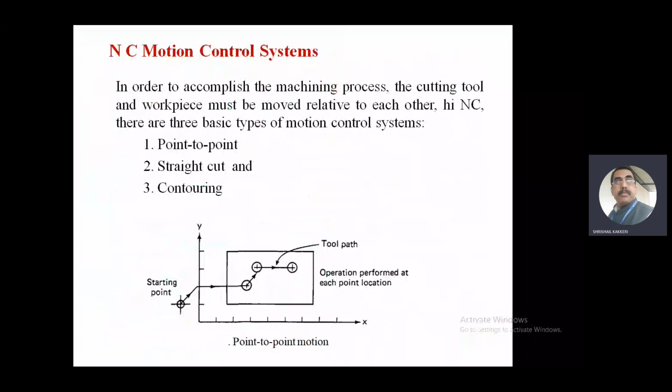Slowly it will be going. So what happens if you have contoured motion? It doesn't have any application, correct? Unnecessarily it will be wasting time. Manufacturing time will increase and machine cost will increase because unnecessarily the tool will be moving slowly, to perform a job of 5 minutes it will be moving for half an hour. Is it required? It is not required. A defined path is not required for me. It is simply going in the air. It is not doing any kind of machining.